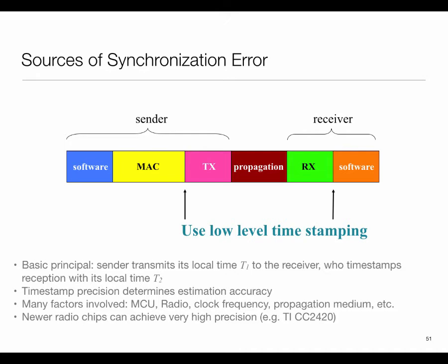So how would you do it more accurately? So recall the kind of timers and all I had talked last time around, which most embedded processors have. Would any of those help you out? So one of the capabilities I had mentioned as an example with the LPC1768, but it's pretty much in every processor, including your mbed, which is they have this notion of timer capture. That is, in the hardware unit, there you could assign a pin whose job is that whenever that pin fires, then the current value of a counter is copied into the register, and that happens immediately. No software intervention. It's almost like you have a dedicated hardwired interrupt handler for that thing, okay, whose sole job is to take a snapshot of the counter. Okay, and as long as you can then read it out before the next time it comes, you're good to go.